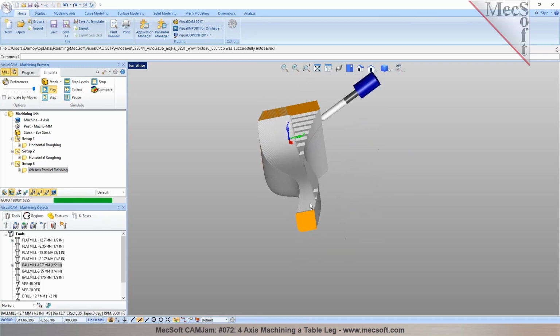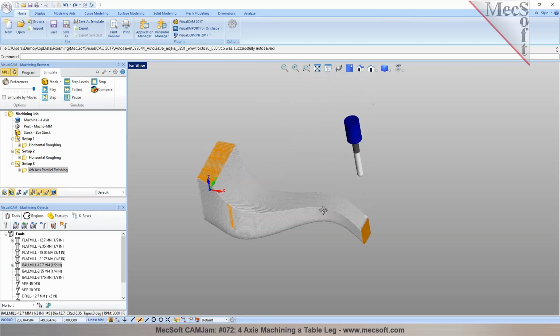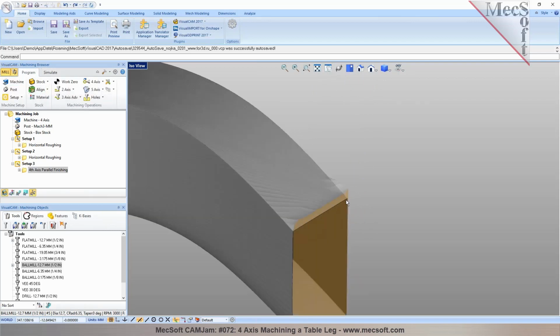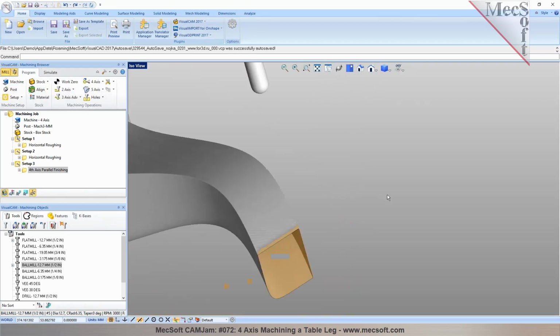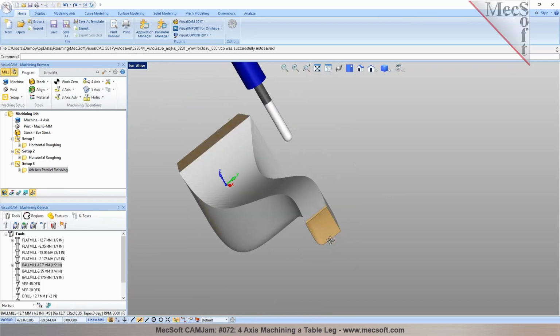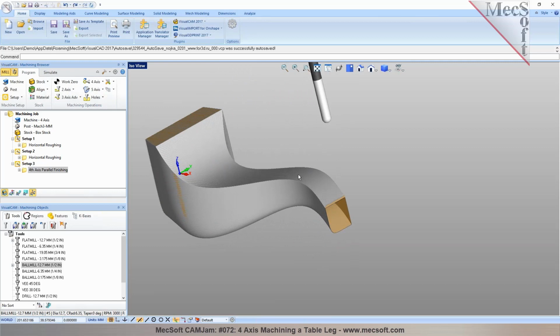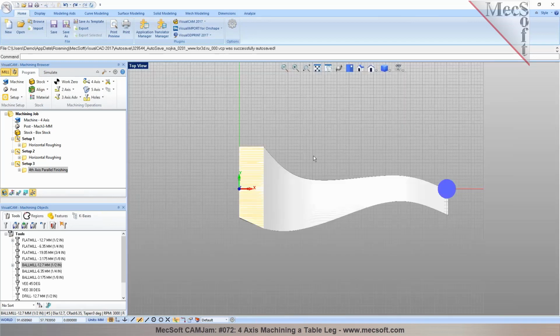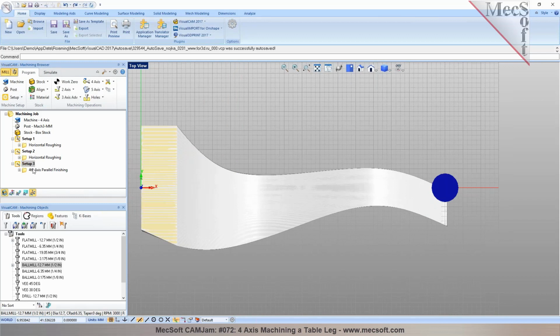So you'll notice that on this particular part, for most areas, most part of it, we were able to program it using a continuous operation. Right? Perfect. There's a small section in here, since the section was dipping below the rotation center, we weren't able to cut that area with a continuous 4-axis toolpath. Now you could do a combination of indexed operations. You could do rotate table setups, maybe rotate it like a 45 degree, or you could pick one of the orientations and program it, or you could even just do a 3-axis looking down from the top orientation.